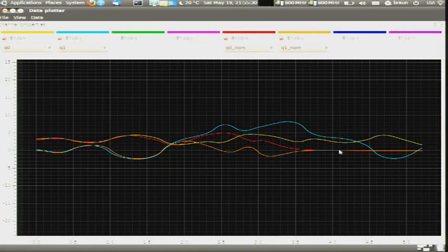That's nice. The bad thing is that the actual trajectory, if you disturb it just slightly, doesn't end at the goal at all. It does something completely different. So at first, it looks as if it's actually almost on the trajectory we want to follow, but then it diverges. And of course, it's clear because we have small disturbances and they grow because they're not controlled. We don't have feedback. So direct collocation is only one part of the answer. We still need feedback. We can't go completely with open loop control.